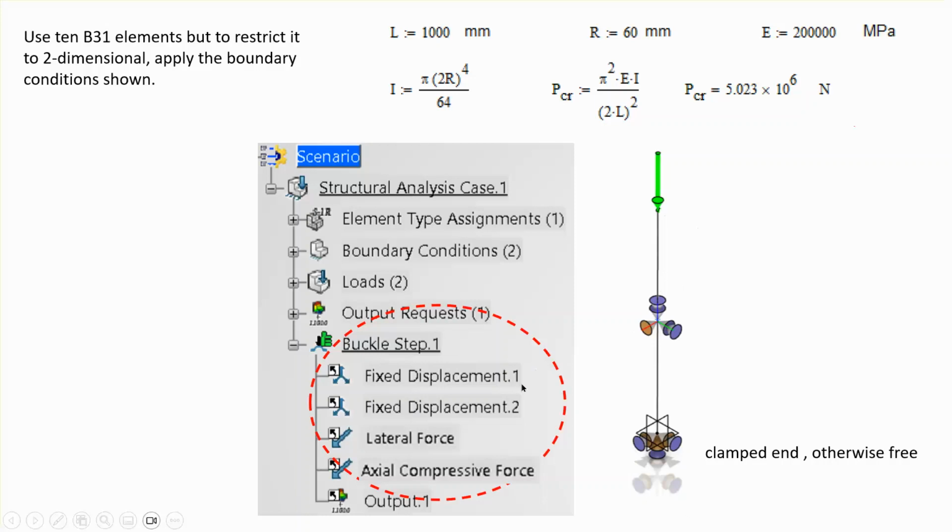So in the buckling step, I did not have any other force showing up. There was only a single force acting. And of course, the theoretical solution is something along this line. I used linear three-dimensional elements, but I did introduce some restraints so that it essentially converted it to a two-dimensional problem. I did the fixed-free problem. I didn't want to use a complicated geometry because that masks the issue, and you spend a lot of time creating the model, but the basic question is not answered.